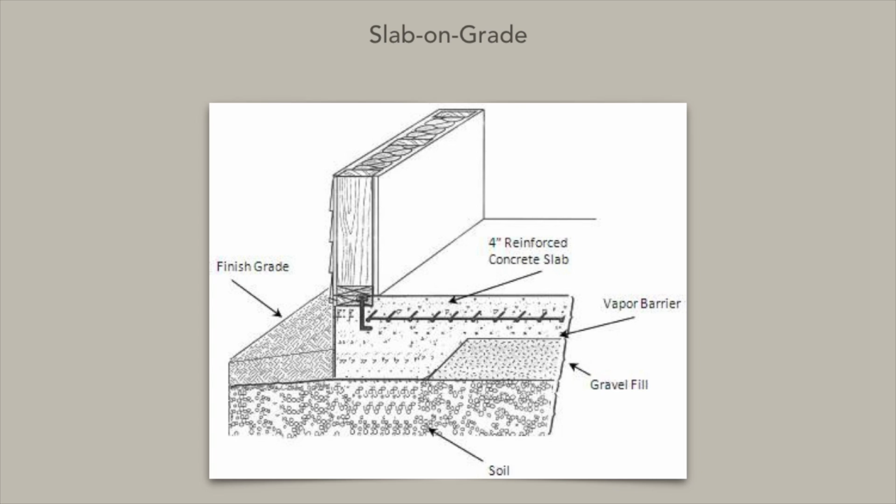A slab-on-grade foundation is a concrete floor installed on undisturbed soil below the topsoil. This is done similar to a basement floor. The topsoil is removed from the ground, forms are installed, and a concrete pad or floor is poured. The concrete pad is reinforced with metal. The metal reinforcing can be either in the form of half-inch or 3/4-inch bars tied together at right angles, or heavy wire mesh can be laid in place prior to pouring the concrete.